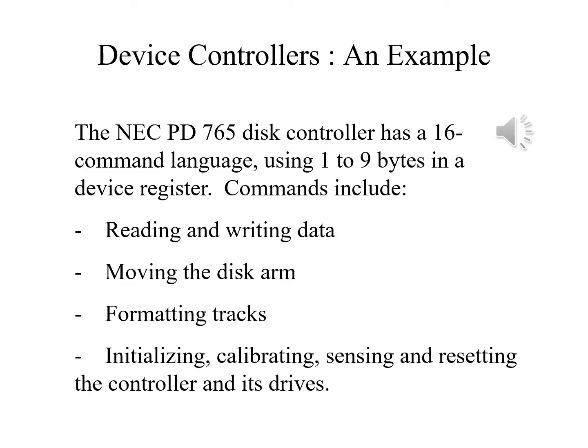The NEC PD765 is an example of a disk controller. For all practical purposes, it is a specialized processor. It has a 16-command language, with the command being executed being stored in a device register. The commands can involve transferring data or various control functions, such as moving the read-write arm, formatting tracks, and so on.